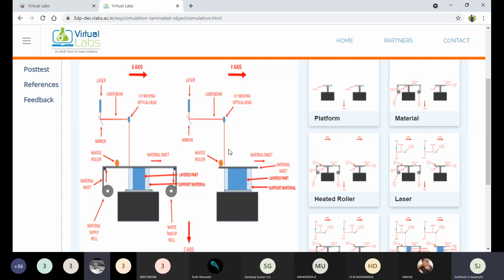Clear now? Yes. Instead of using the powder materials, metallic and non-metallic, directly we are using... The only thing that changes here is, suppose you are comparing this LOM process to the previous one. In the previous one, we supplied the powder materials from the bed. On this side there will be the bed, completely filled by the raw materials in the form of powders. Instead of the powders, here we are using thin sheets, and we supply the thin sheets.